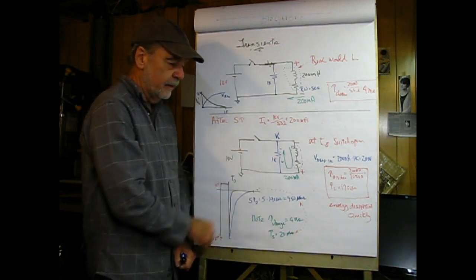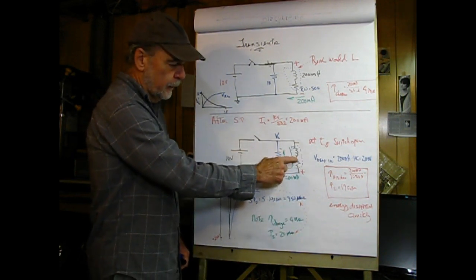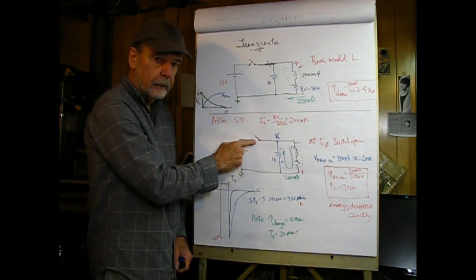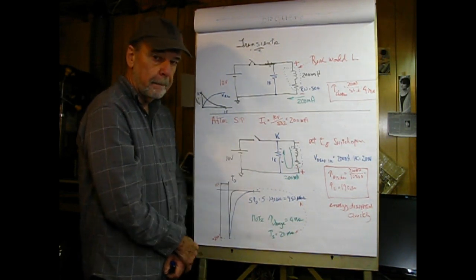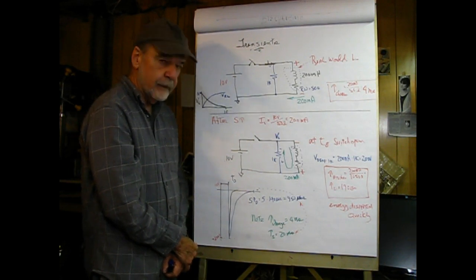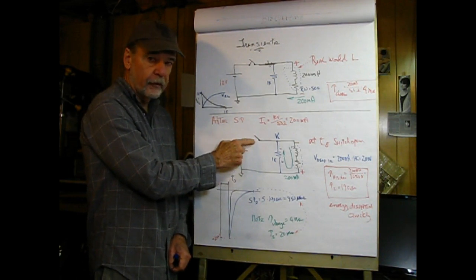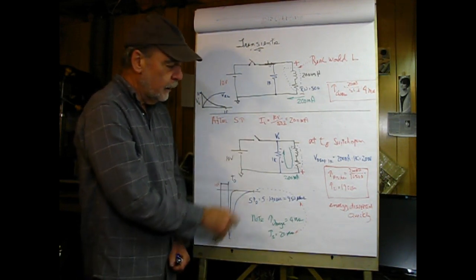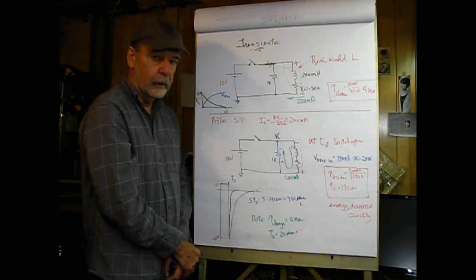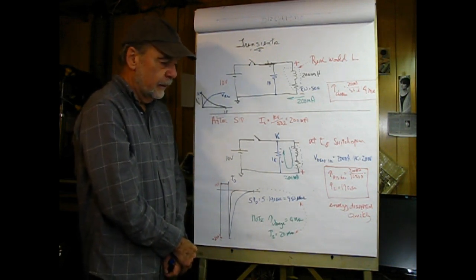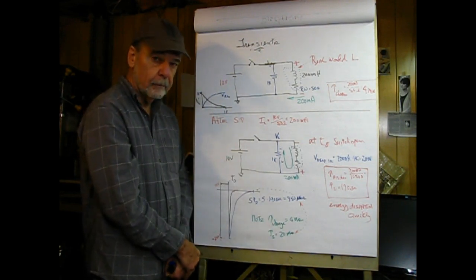Now what if we didn't have a resistor here? What would the discharge path be? Well, the polarity would be this, and even though the switch is open, current would flow through it. How does that happen? It arcs across the switch. The time constant in that case would be very, very small, and the voltage would be very, very high. Most likely we get an arc. Whenever we have an arc, we move metal, and that's bad, because switches wear out, relay contacts wear out, and so forth. Now where this really plays well is in making spark plugs work in your car, and that's